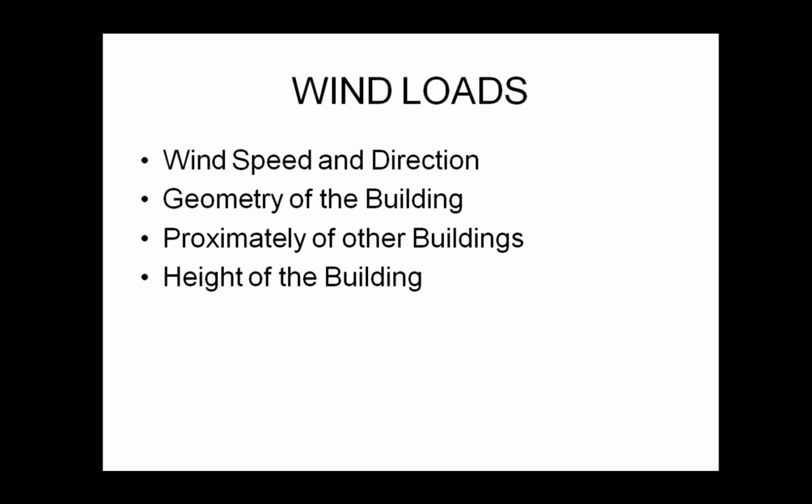Okay, if you're building in an area that's surrounded by other buildings, you'll probably have less wind loads. You could have shear loads on those areas, like on the streets. Okay, but direct hits from wind, you're more likely to have those on buildings that are at the exterior of the island, 1st Avenue, 11th Avenue, wherever you might be. And the height of the building. Of course, the higher up, you're exposed to higher winds. The higher up, you also have less buildings around you to help deflect the wind or serve as windbreaks around you.